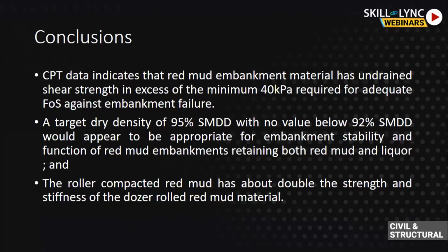So, one such thing is that you have to know what the material is. The material which has been used for compaction is one of the most important factors which helps you to determine and achieve the required compaction in a particular project. Although, as I told you earlier, normally people say you have to achieve somewhere between 90% to 95%. That is what is expected from any contractor or any company building embankments, roads, dams, and all these things.